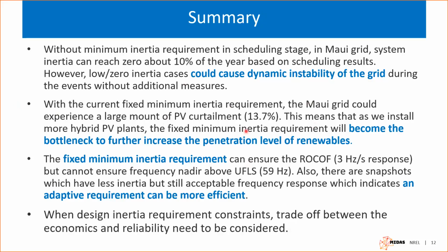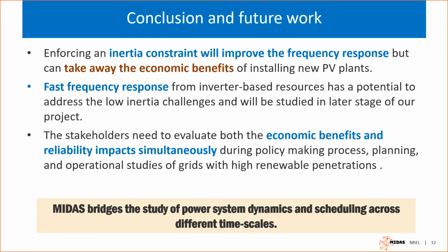if we don't consider converting the synchronous generator to the synchronous condenser, that will easily become a bottleneck to further increasing the renewable penetration level. And also for those inertia requirements, it looks like there is a need for adaptive requirements. And when we consider those things, we need to consider the trade-off between the economics and the dynamics.